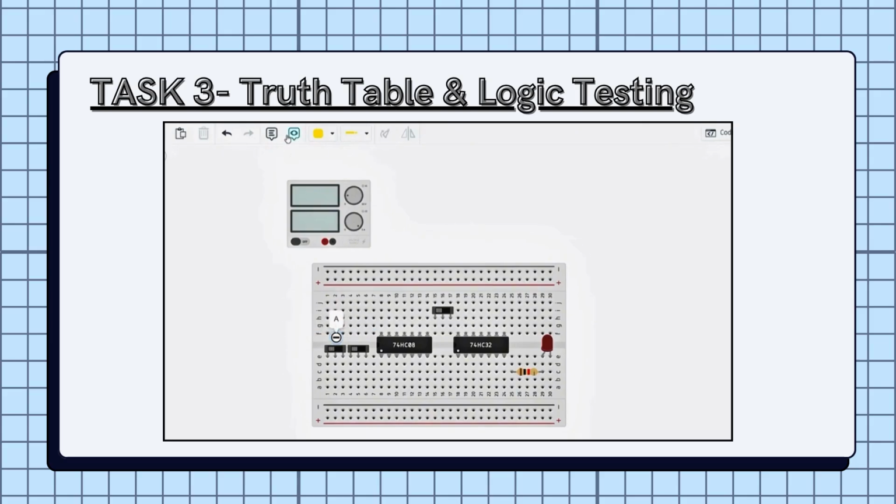74HC08 for the AND gate and 74HC32 for the OR gate. Both ICs are placed with the notch facing up to ensure correct pin placement. There are three switches labeled as A, B, and C. When any switch is turned on, it sends a signal to the circuit.